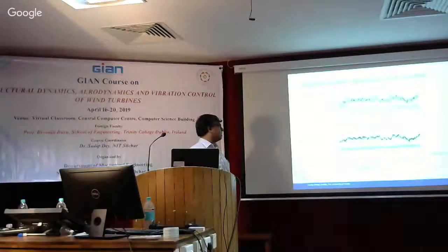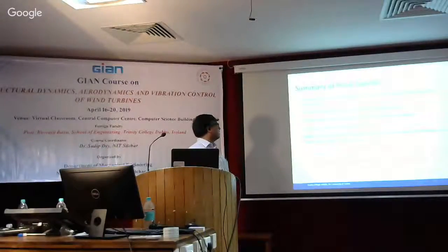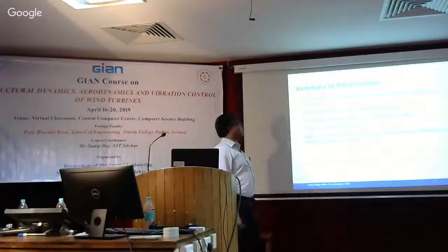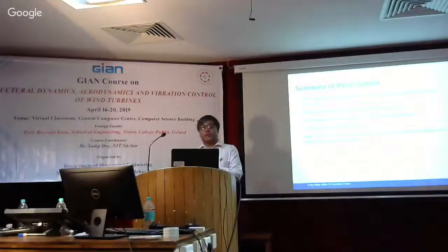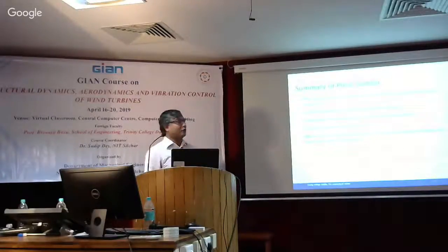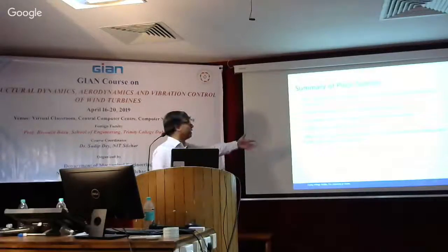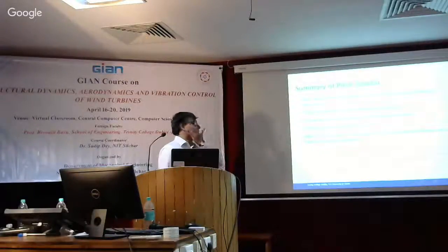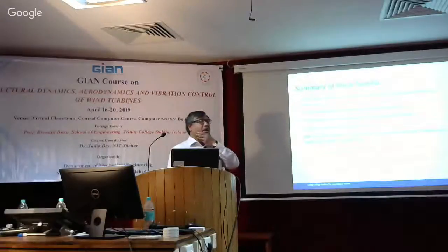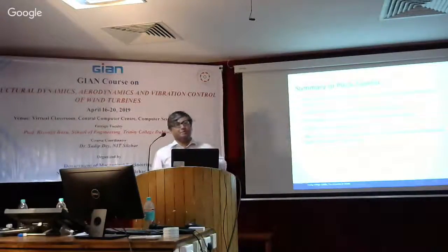Again, similar type of things here. So just to summarize, pitch control is used for optimal power tracking, but also for structural load reduction. Two functions. A few classical and quite advanced algorithms were presented here, which are valid or implementable for fixed speed and variable speed machines.